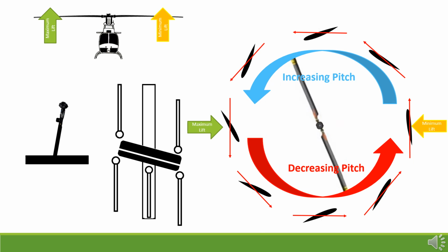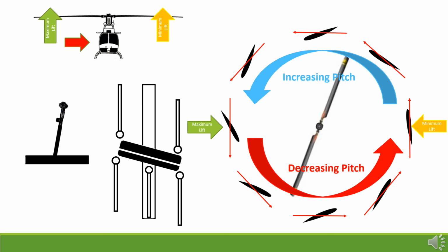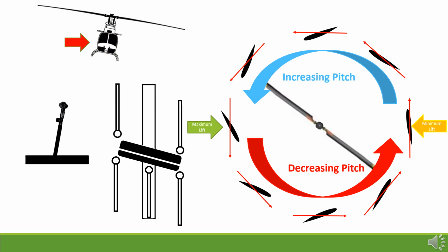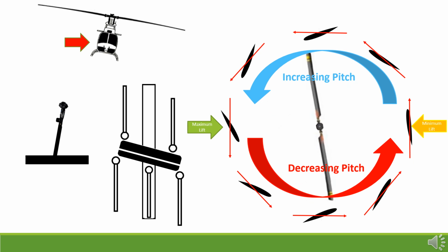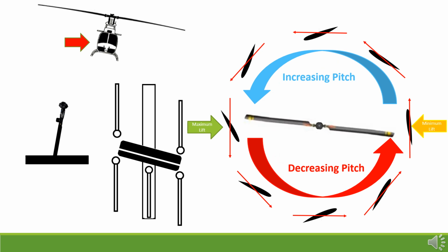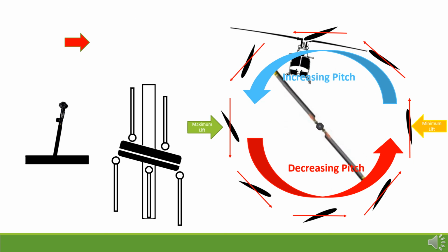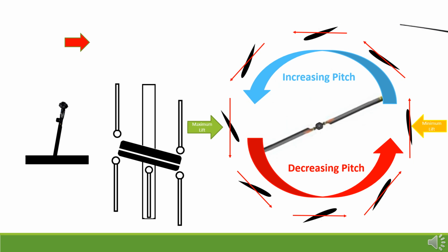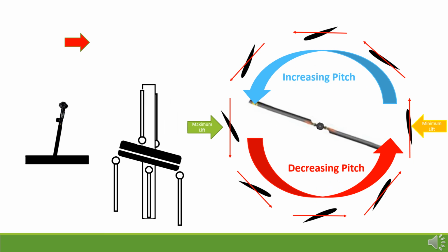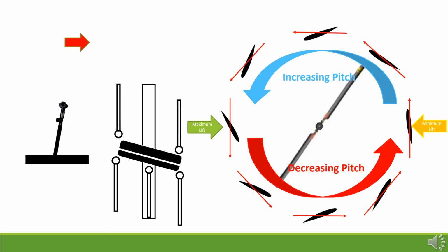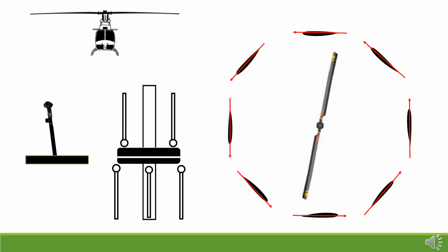When the rotor disc rotates to the left, it produces a force also acting toward the left. It also makes the helicopter roll to the left, thus losing altitude but increasing the rotor disc tilt and increasing acceleration to the left. Again, a corresponding increase in collective control would be required to keep the helicopter from losing altitude. To coordinate a left-hand turn, the anti-torque control must be added to move the nose of the helicopter in that direction.